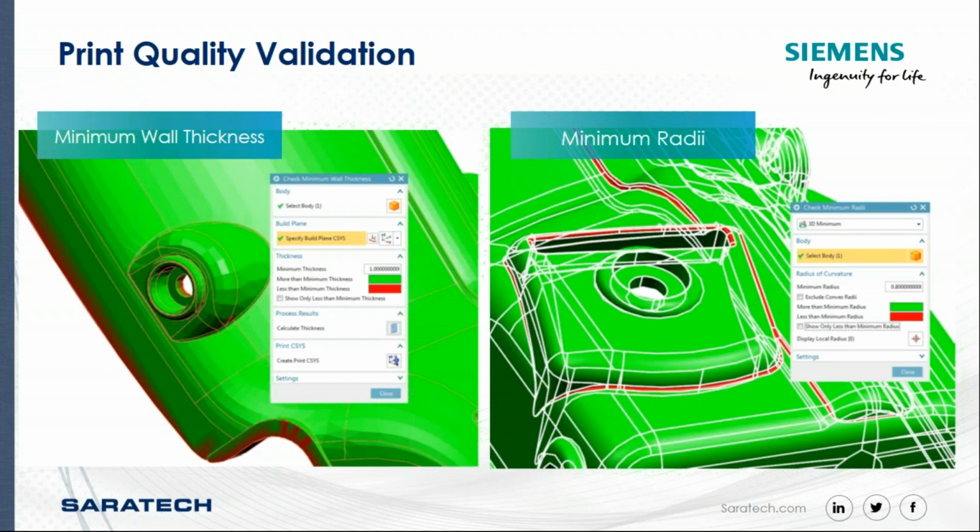So we integrated a series of checks specifically for additive manufacturing into our NX package to allow you to check your part as you're designing it for areas where you may have issues. So this shows a couple of the checks. We've got a minimum wall thickness and minimum radii checks, and every printer, no matter what kind of printer it is, is going to have a minimum threshold for features it can accurately reproduce.